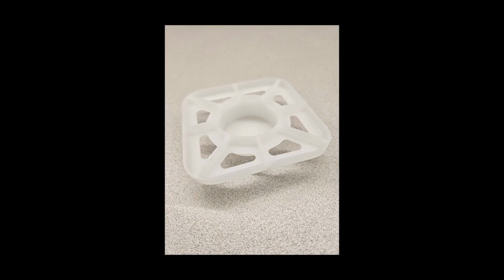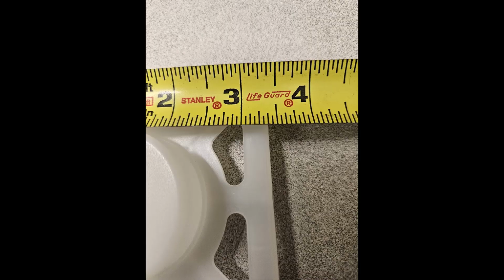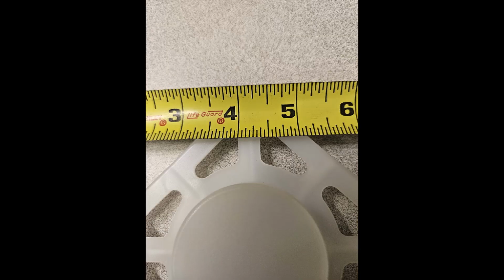To conclude, I want to go over a basic procedure for creating the blocks that are most of assignment number 4. For demonstration purposes, we'll use one of the plastic plugs that hold a roll of plotter paper in its shipping box. Its overall dimensions are 4 inches by 4 inches, and it has a 2-inch diameter circle at its center. Its thin ribs are 1/16 of an inch thick, and its flanges are all 3/8 of an inch wide.